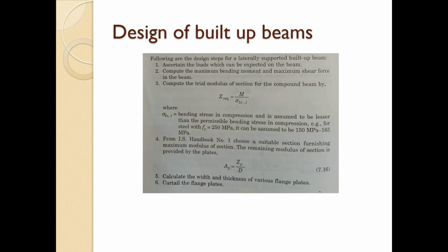Now the design of built-up beams. Following are the design steps for laterally supported built-up beams. Ascertain the load which can be expected on the beam. Compute the maximum bending moment and maximum shear force in the beam.